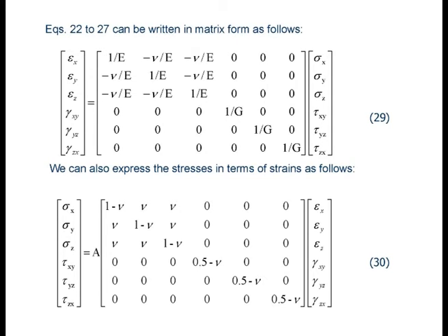Now, the first thing you must understand is this: when you play with a finite element program, internally and unknown to you, of course it's invisible to you, the program is playing around with a 6x6 matrix whenever it has to set up a relationship between stress and strain. It's always playing with the 6x6 matrix. So the only question is, what is this 6x6 matrix that it is playing with? And this is for full 3-dimensional analysis.